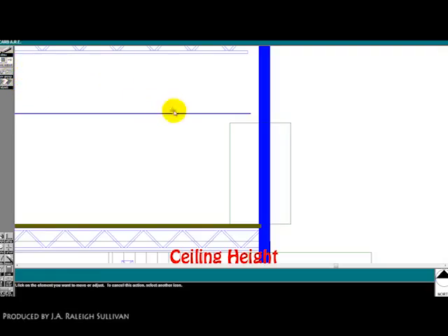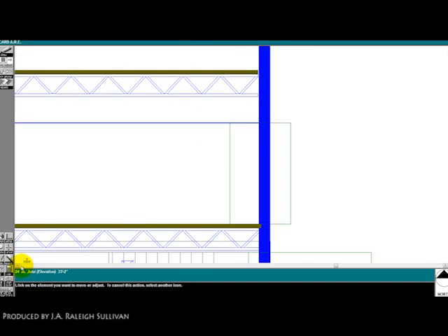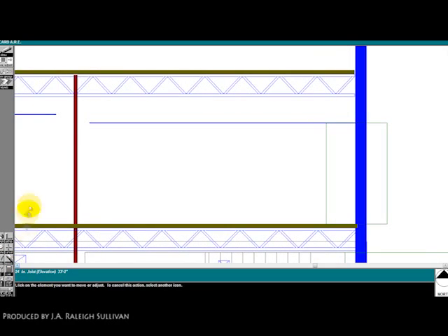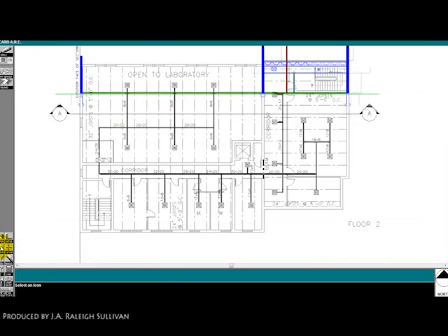And then move adjust, grab that ceiling, move it over, get it to be right at 9 feet. Move the joist down a little bit so it's within reach. Scroll over, pull that ceiling over to touch the firewall. And I'm going to extend the sketch rectangle so it goes into the corridor. Make sure I get the corridor ceiling at the proper height as well, so I can touch the wall. I'll zoom out.